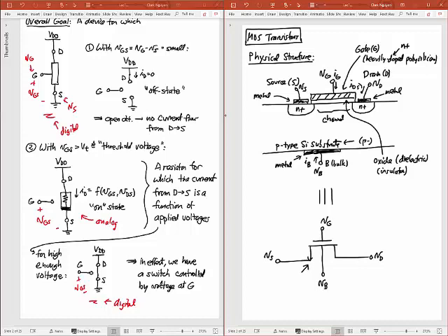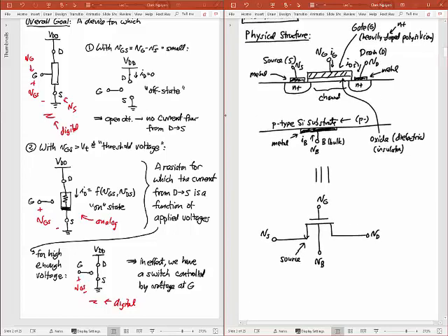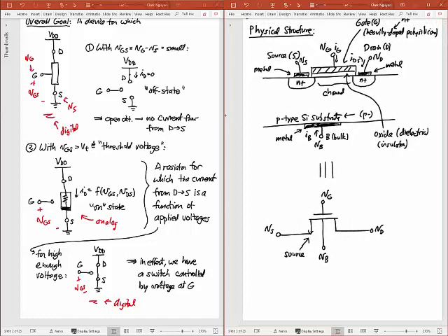Okay, so this arrow there, that corresponds to the source, and so that tells you, if you know where the source is, you know where the drain is, right? Because the drain is just on the other side. But that arrow tells me where the source is. And in general, the reason why we make that arrow is because when we're actually drawing circuits, that's going to be the direction of current. Okay, under normal flow, that arrow will tell you the direction of current, so that helps you quite a bit. All right, so that's the physical structure of the device.